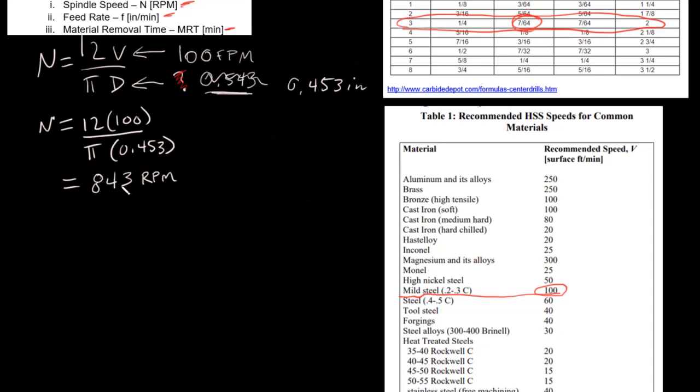Yeah, so this is quite a bit smaller value than the center drill. The center drill had a 0.109 inch diameter cutting tool, and I think it was around 3,500 that the RPM was set at. And really, as this number gets bigger, N will become smaller. And that's sort of the relationship there.